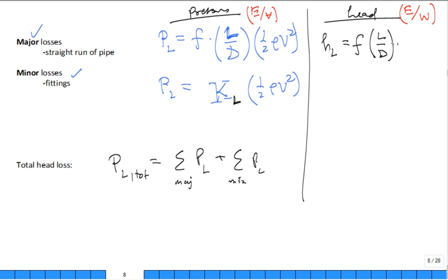It's multiplied by the velocity head. So what is going to be this right term right here? 1/2 v squared over g. Isn't that right? Doesn't that work out? Remember 3 forms of Bernoulli's equation? Pressure, energy per unit mass, and head. And now we just are jumping between. So when you see it in a different form, you're like, oh, he's written it in terms of head. It looks different. It may look wrong, but it may be correct.